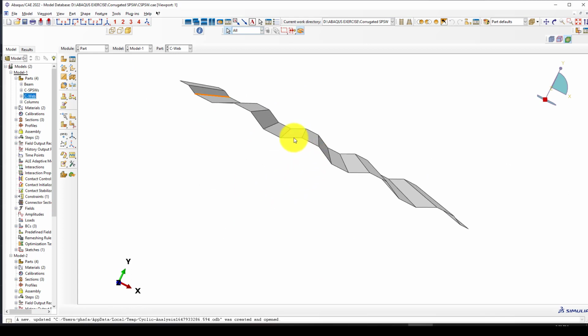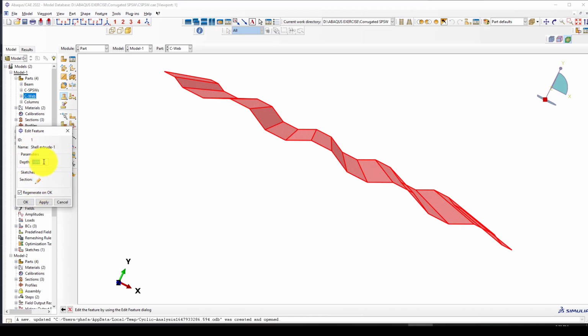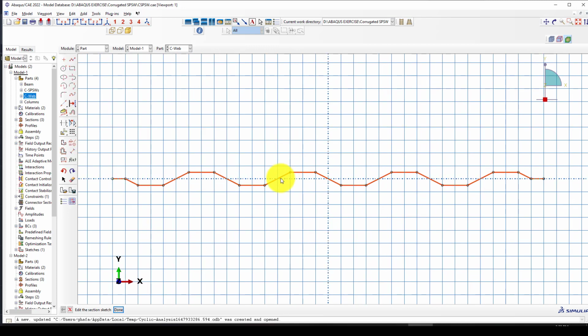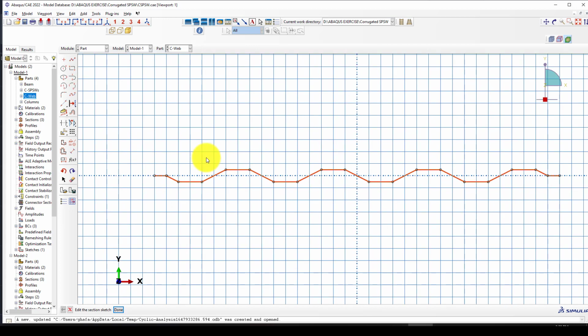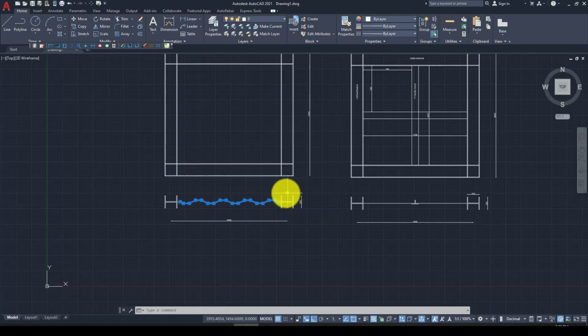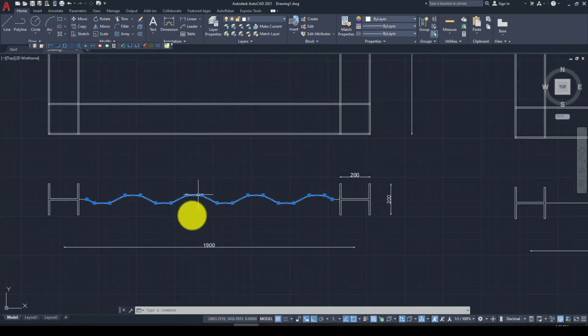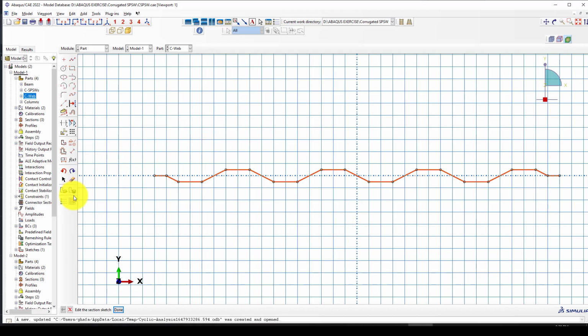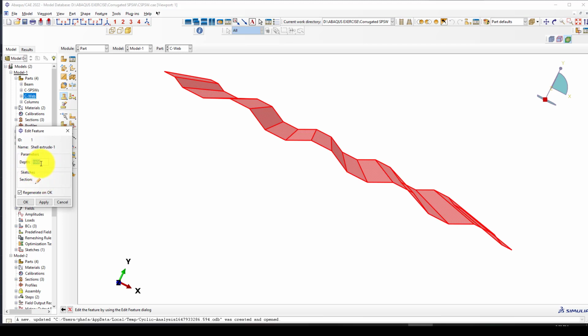It's a little difficult to model in here, but the height is 160, and you can model using a line, such as you can come here and then come back and here like this. But I recommend you model that corrugated line in CAD, and then you can import this line as a part, then you can bring that part and extrude it. The extrusion depth is 1.6 meters.